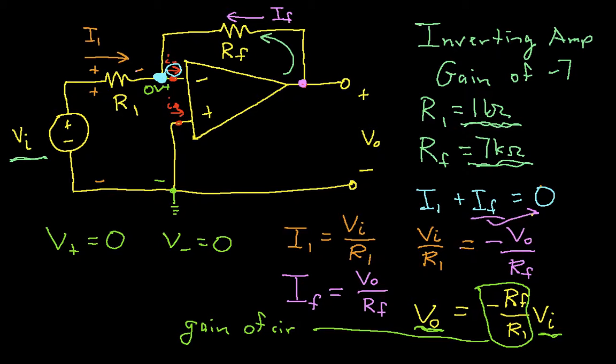So you size R1, and from that RF, taking into account current and power consumption. For a typical op-amp application, R1 of 1 k ohm is a pretty good first guess, but again, you'd want to make sure that you've got it right.